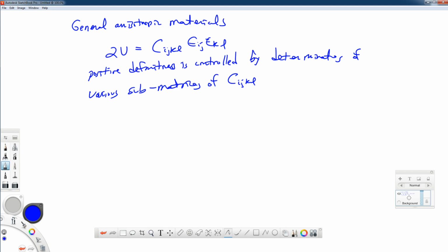So they will have some statement like nu xy has to be greater than 0, or has to be in a certain range. There are certain conditions that have to be met from a theoretical perspective that they will enforce in their finite element code. It helps with a few features. It helps getting the right stress fields, but it also ensures this positive definiteness of our potential function.